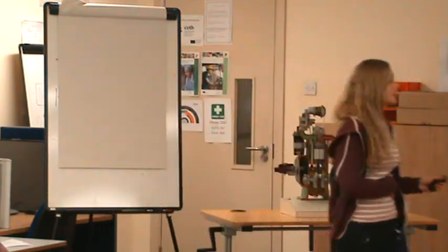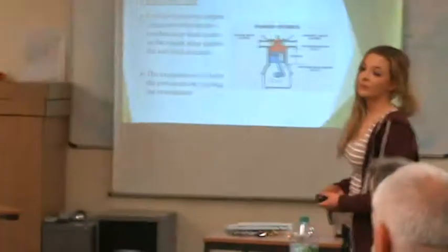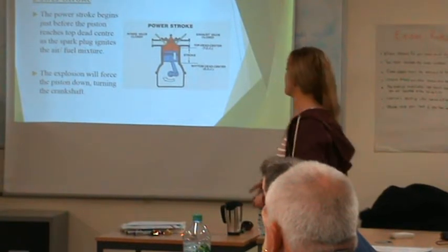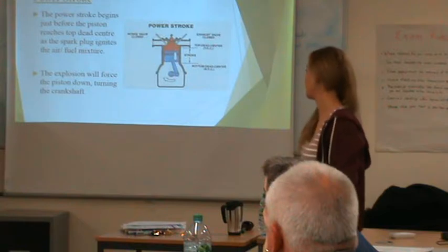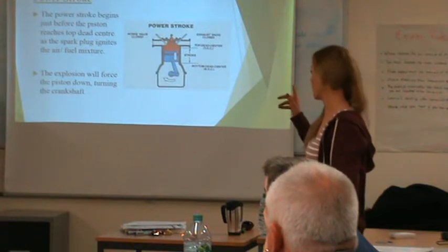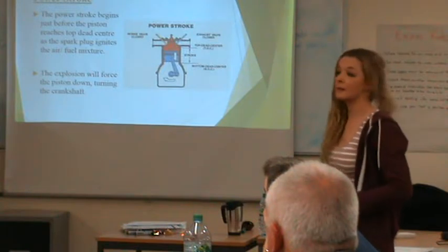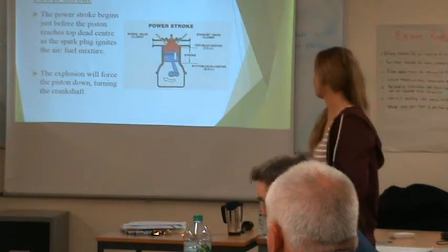So this is the most important stroke now. We have the power stroke. The power stroke begins just before the piston reaches top dead center and the spark plug ignites the air-fuel mixture. Remember earlier on I was saying about the spark plug, it has to ignite at a specific time. So that's going to be during the power stroke, you could say. The explosion will force the piston and turn the crankshaft. So the piston is travelling downwards.